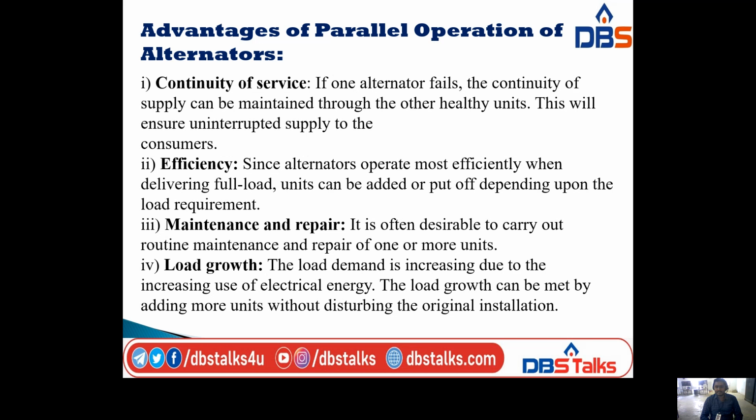And coming to the maintenance and repair, it is often desirable to carry out routine maintenance and repair of one or more units. And coming to the load growth, the load demand is increasing due to the increasing use of electrical energy. So the load growth can be met by adding more units without disturbing the original installation. These are the advantages of parallel operation of alternators.